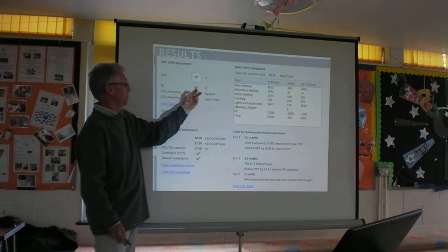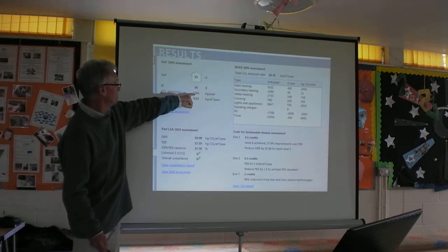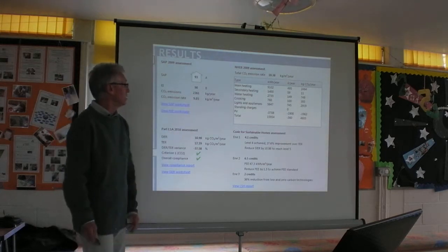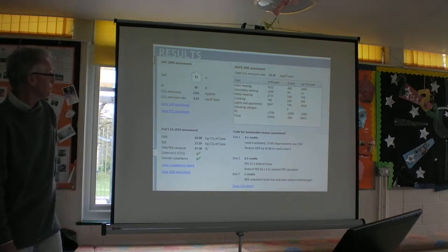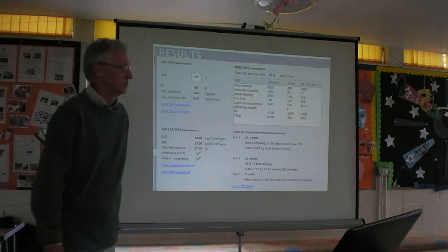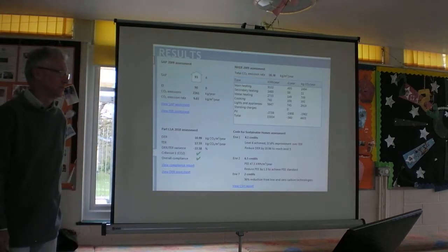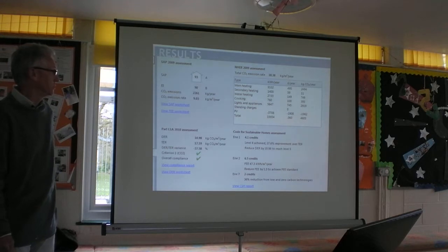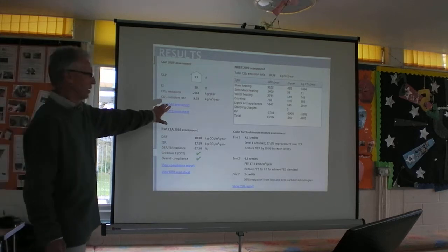I don't know why you've got the 2, 90B. It tells you what your emissions are. So our emissions from this house, putative house, are 2.2 tonnes per year of CO2, 9 kilos per metre squared. To put that in context, the 2.2 tonnes, what would a Victorian terrace of a similar size be? 10. So it's about 4 times better. Yeah, probably better than that actually. Don't take these as absolute values. They're just a screenshot of one house. It's that sort of scale.